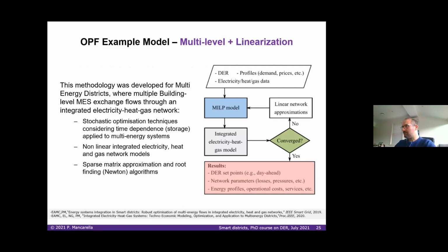And in this, the way that we did the modeling was to basically say, whenever you need to control resources, you can't beat a MILP controller, so a mixed integer linear program, to develop a controller for resources in a building or resource of a sort of community energy center. And then you would have the set points developed by your MILP controller.